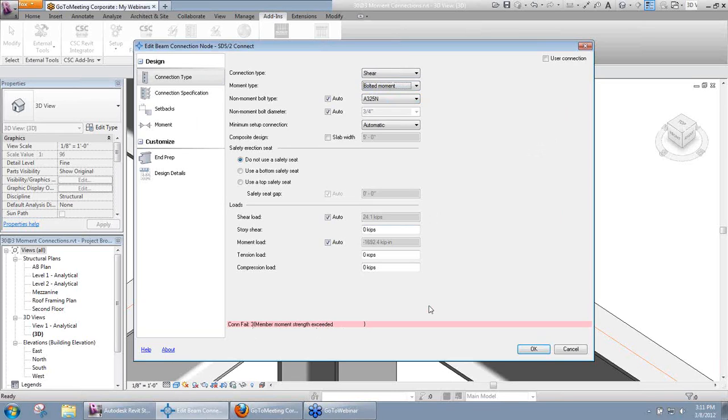So what's happening here is the reason this is failing is the automatic load that's calculated here for the moment. This is actually 85% of the max beam moment, but that's before holes are present in the flange for the moment plate. So after those holes are drilled or punched in the flanges for our moment plates, the max moment of that is reduced.